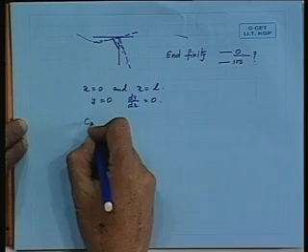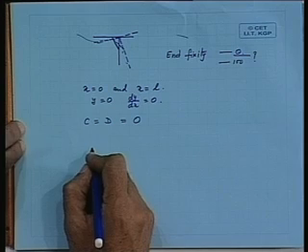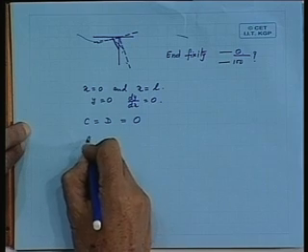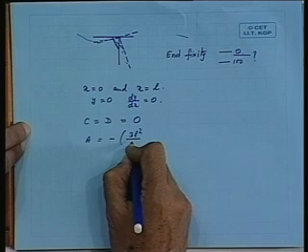So, somewhere here the stresses are coming. At this moment I am ignoring that. If I ignore that, then because of this particular pressure, my structure should deflect like this only. Putting these boundary conditions, we get the values C is equal to D is equal to 0 and A is equal to minus. I am straight away writing these values.